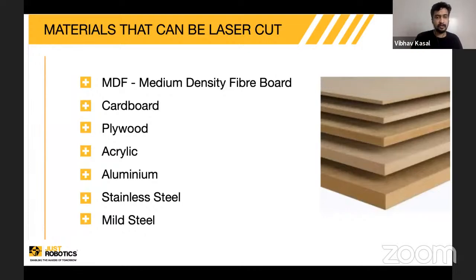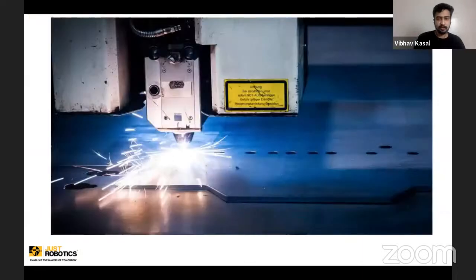And laser cutting is only two-dimensional. I mean, when I say two-dimensional, it will only cut like this. It won't cut at an angle. So it is only two axes it can go through. So any flat drawing image that you give, it will simply cut and give. Then you have to pop it out from that sheet and you can start using it.